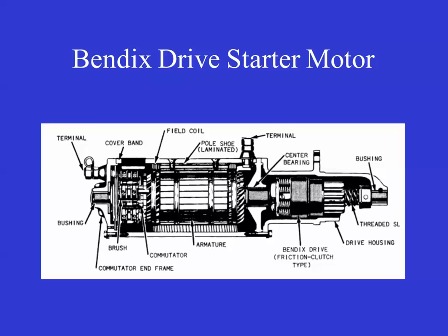Now, a Bendix starter is very common for the electric, especially in automotive. When you look at this, the Bendix itself is what is going to engage the drive gear. You don't want your starter engaged all the time, because it is turning at quite a high speed and it's engaging with the flywheel.